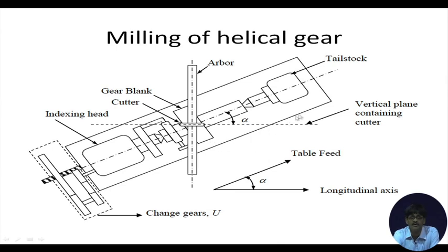This is the table of a universal milling machine seen from the top. This is a horizontal column and knee type universal milling machine. Why horizontal? Because this is the axis of the cutter, the axis of the arbor which is holding the cutter. Arbor is the shaft which is holding the cutter. This is the cutter. Now, how does it correspond to the cutter that we have seen in our drawings? This is that rotary disc type cutter. The disc is being seen from the top, not the circular part. I mean the width of the cutter is seen in this direction.